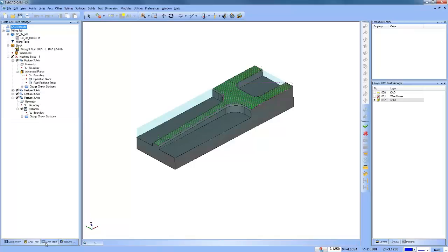So if you've ever wanted to extend the toolpath out past the edge of the part, this is one of the ways in which you can do it. Normally, a lot of times, the way I'll accomplish this is with the premium surface-based toolpaths, because they have an extension option in there. Prior to that, it would really just be extending surfaces. So if the toolpath is driven on the surface, you would extend the surface out.